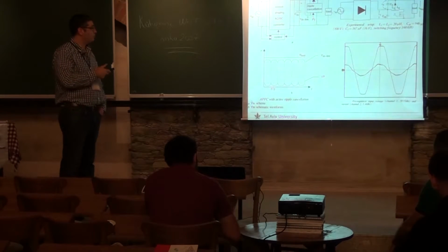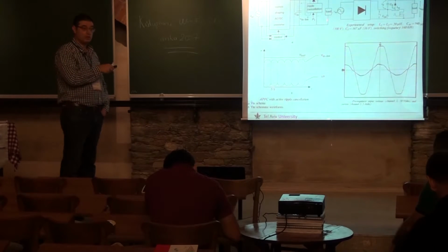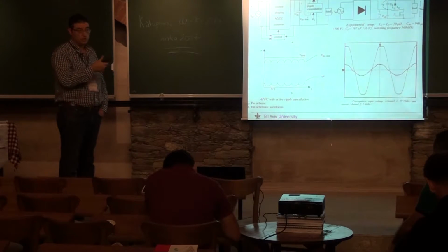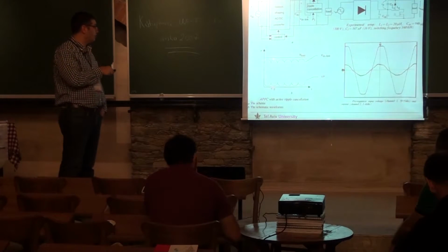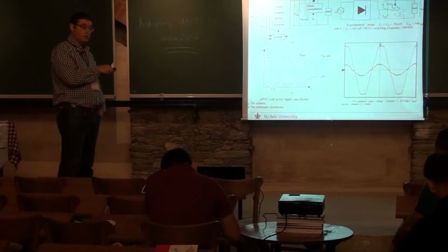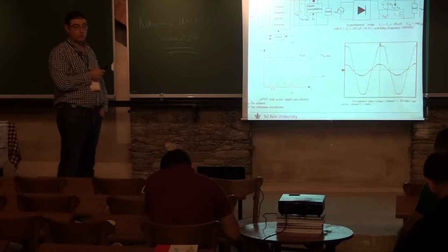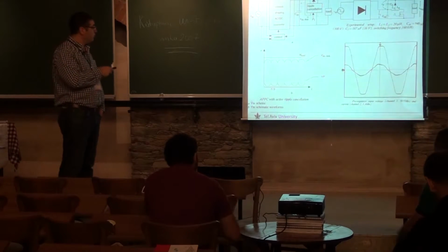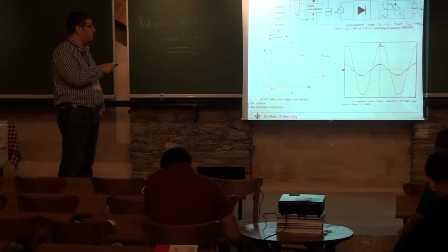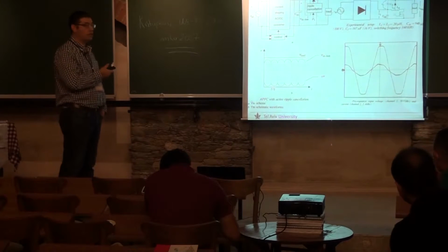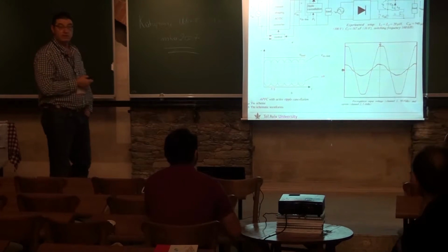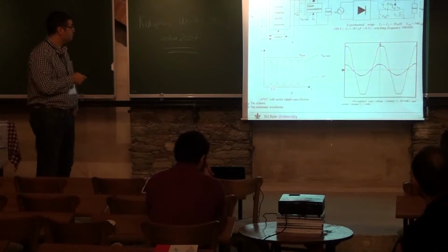Okay? Now, again, this is going to be a poor converter in terms of efficiency, because first of all, it's a low power converter. So that's one reason for low efficiency. Second, its output needs to vary a lot. So that's a second reason for the poor efficiency. Even though this converter has a poor efficiency, only a very small fraction of the entire power goes through it, and it is being processed by it. So the losses, at the system level, are not that much.